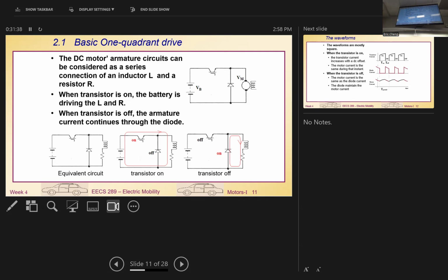So using this method, turn on, turn off, we can control the motor speed within a certain range. Of course, here you can see some speed ripple. But in fact, we use really high frequency switching, so what actually happens here is like that. With such high frequency, you probably cannot feel any ripple, because we use this on and off to control the speed variation in this range.